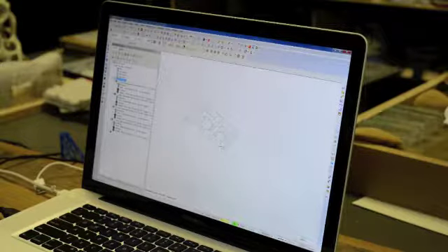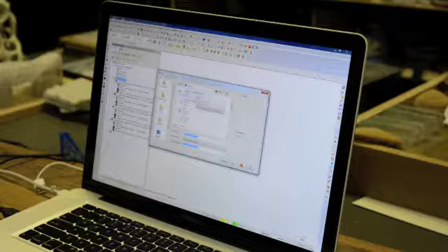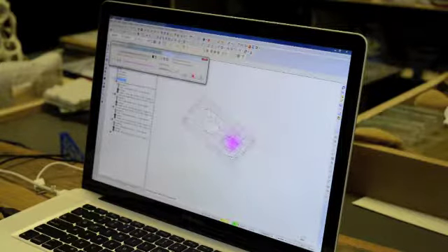And did we do change recognition before? No. Another thing is change recognition as well. So in Rhino, say you made an edit, like you wanted to fill in this hole, for example, you can go over here and do change recognition. So we would select that Rhino file again. I'm just going to do it, and we'll delete it. But so then it pops this up, and geometry display, you want to show the incoming file, and it should remove kind of what's existing and give you your updated stuff.